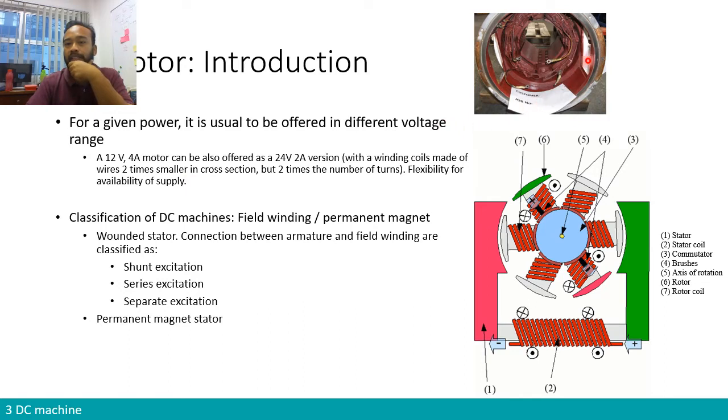So the figure that we have over here is very interesting. Here we can see the winding of the stator, or the field winding. In this case we can clearly see there are 4 poles. There is a section of pole over here, another pole over here, and there should be 2 other poles on top. You have 4 connectors for winding, so there are 4 poles of a field winding. Just now we had a permanent magnet, now we have a winding.